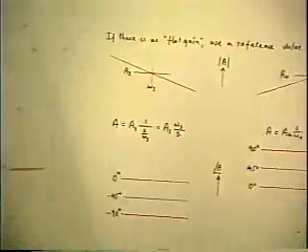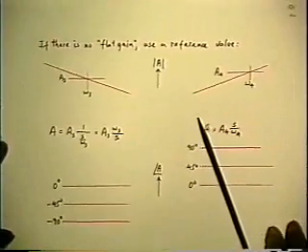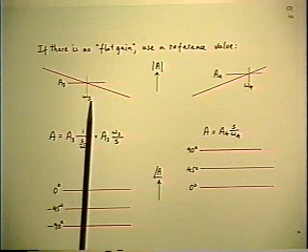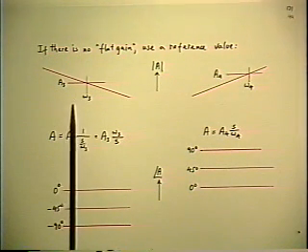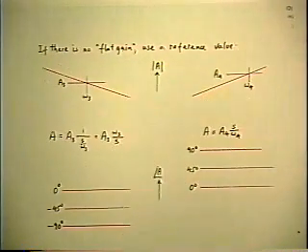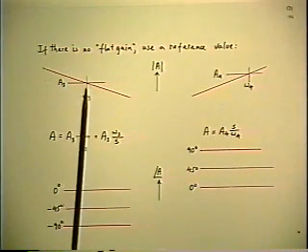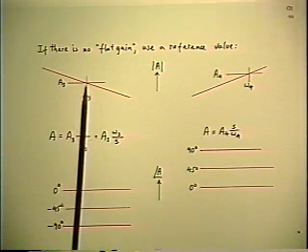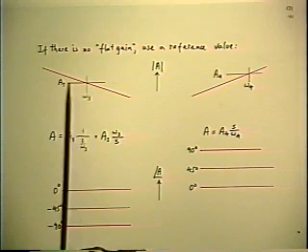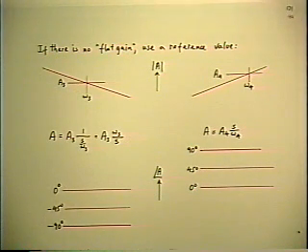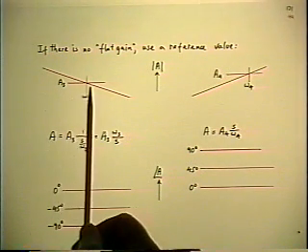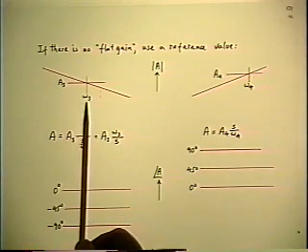So let's look at some special cases. Here's a case where there isn't a flat gain. And if we want to write the factored pole zero form, we have to have some means of locating the vertical position of the whole picture. So what you do is you just take some arbitrary point on the asymptote, which has a corresponding pair of values of a frequency and the gain at that frequency. And the expression that goes with it is A equals A3 at the frequency omega 3.